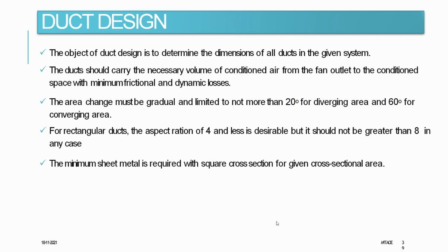The object of duct design is to determine the dimension of all the ducts in the given system. The duct should carry the necessary volume of conditioned air from the fan outlet to the conditioned space with the minimum friction and dynamic loss. That is the basic motive of our duct design.